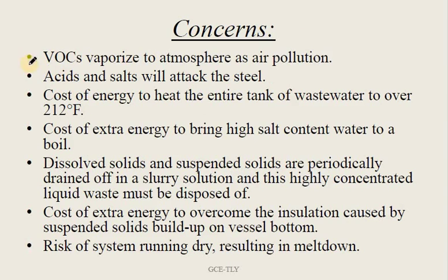The concerns here are the same. VOC is a problem, and acid and salt will attack. That's a problem here, and cost of energy to heat the entire tank of wastewater up to 212 degrees Fahrenheit is a challenge. Then the cost of extra energy needed for overheating, because salt sedimentation is present, needs extra heating. The dissolved and suspended solids should be periodically drained off in slurry solution. And since this is formed in slurry solution, removal of this wastewater is a problem. Then risk of system running dry and meltdown of the evaporator is a problem here.